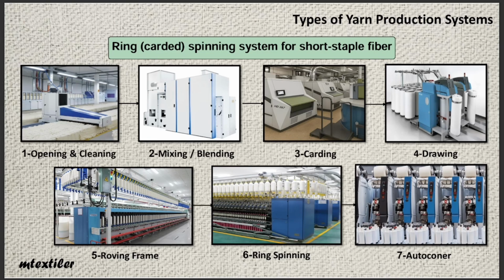During this process, defects may also occur in the produced yarn. In the autoconer machine, in addition to removing these defects, we can unwind the yarn from the spinning bobbin and join it together in this machine so that in subsequent operations, there will be no breaks at these points, and the overall structure of the yarn will be well formed. Because these joints, if not formed properly, can also cause yarn breakage and lower production efficiency in other machines.